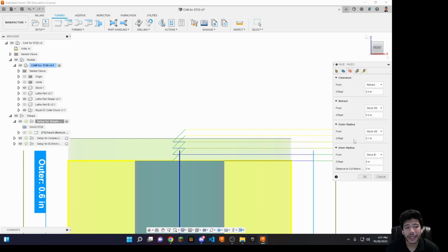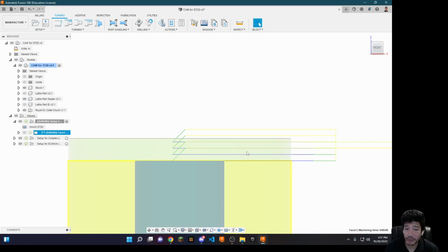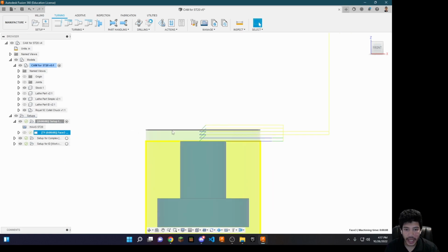Actually, never mind. You cannot control this. So you have to place the stock exactly where it is stated. And if anything, it has to be further in the chuck than further out. Because if it's further in, it will not make the cut. But if it's further out, the tool is going to take a much bigger cut than you programmed in. And with that, we have done our first operation.